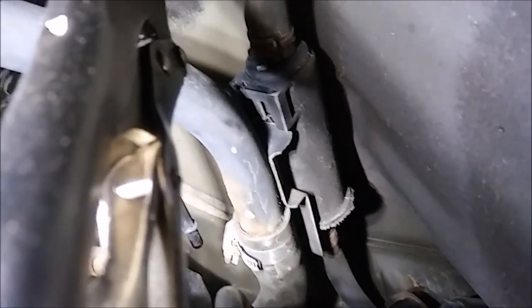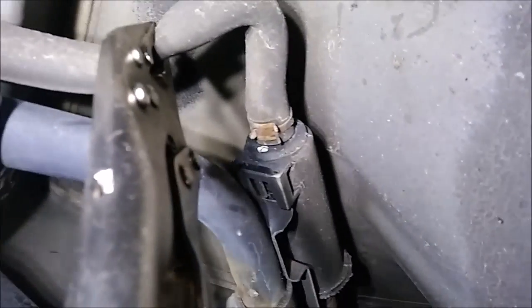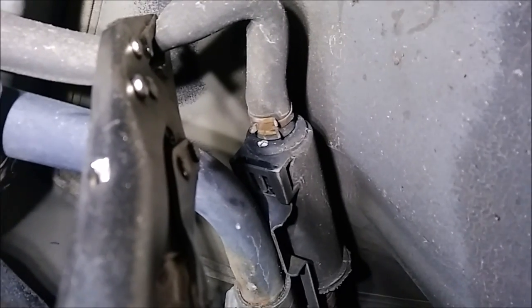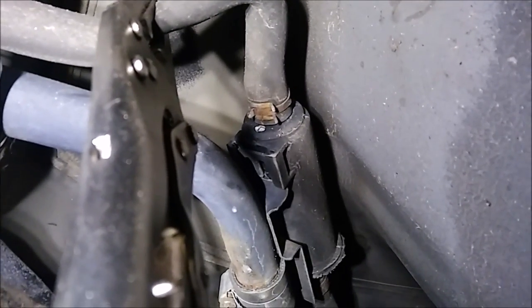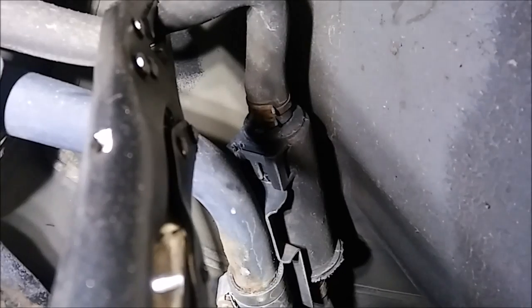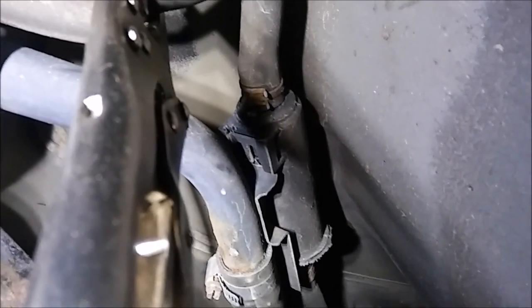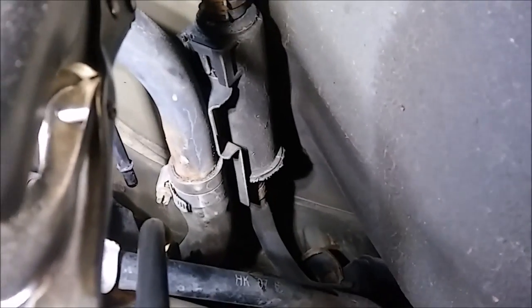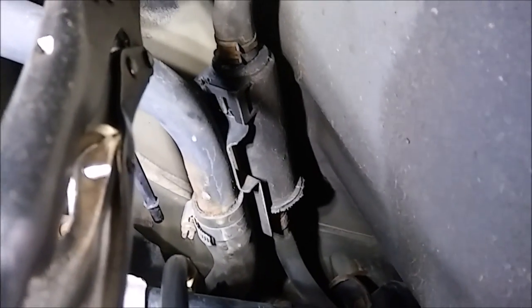I'm just thinking about where I can plug into. We do have this vent valve filter here. What we can do is potentially just isolate the vent from the system altogether and just smoke test the tank and canister and look for our leak there. If we don't see a leak there, then that kind of points towards the vent valve itself as being the issue, and we'll have to rip this wheel liner out and access that.